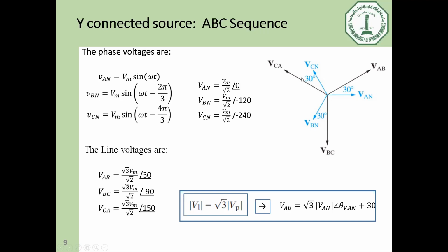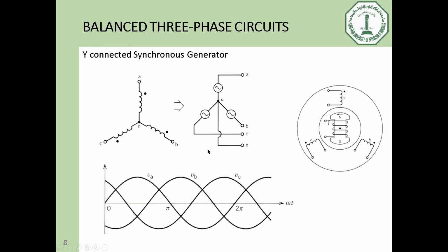If you would like to calculate the line-to-line voltage from the star connection, we can return back here again. Line-to-line means between A and B. So how can we calculate VAB, Shabab? We can make a loop, is it right? And